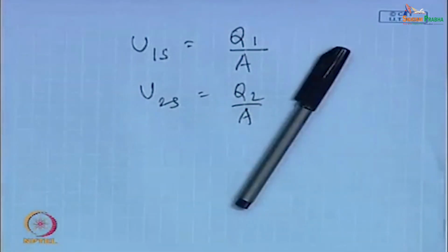So, therefore, whenever we refer to a fluid in two phase flow, you will be finding in several journals and textbooks, they mention the velocity of fluids. Please remember, the velocity they mention are the superficial velocities. We come across the superficial velocities; in situ velocities we find out only when there is a definite purpose for it, but for the purpose of characterizing a fluid, we do it conventionally by using the superficial velocity of the fluid. So, therefore, these two extra definitions had come up.